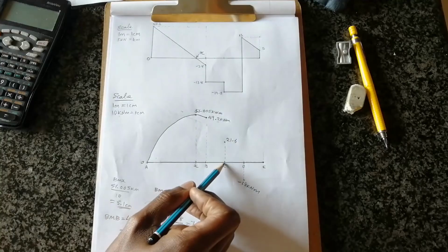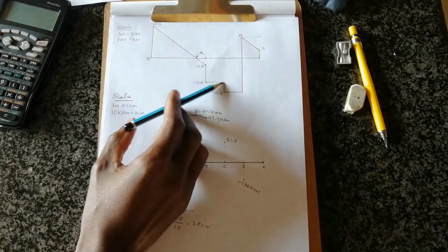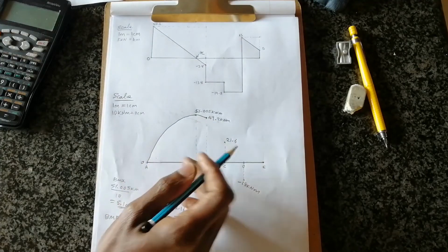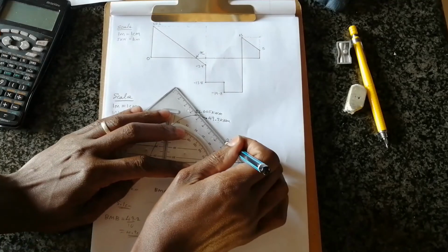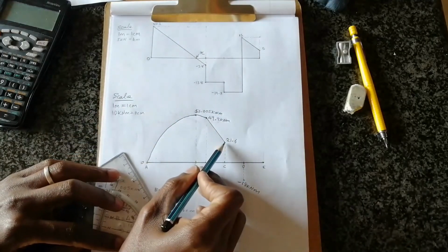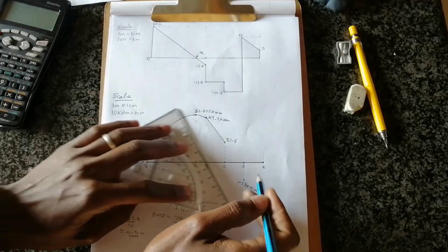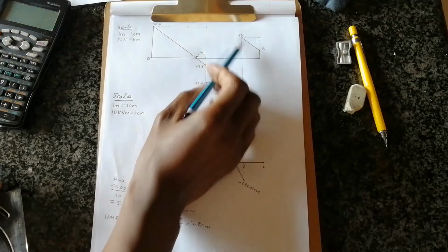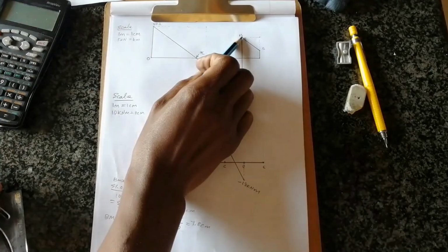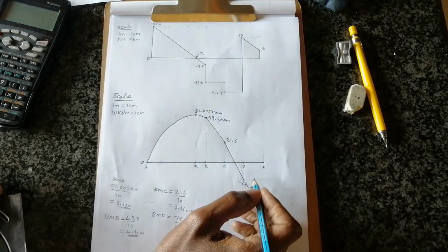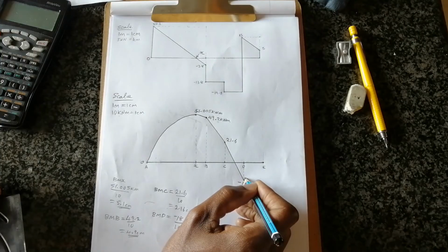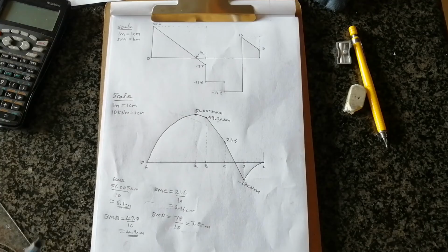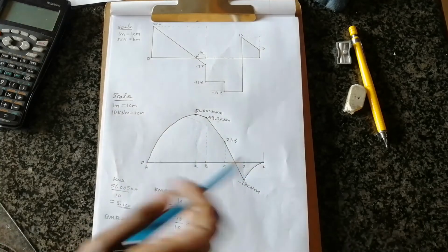Then from B to C, when we look at our shear force diagram, it's just a horizontal line. So the two points from 49.2 to 21 will be joined by a straight line. From point C to point D, again you connect with a straight line, using your ruler. However, for the last part from point D up until E, we have a uniformly distributed load, and this will also be a freehand curve from that point up until you reach your 0 line. So this is how our bending moment diagram will look. With all those values, they'll give us all the marks for that.